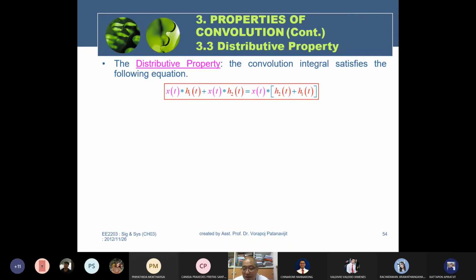But instead of considering it as a single large wide band, we separate it into small narrow bands, maybe 10, 100, or 1,000, and transmit each piece of the signal. Even if some band is interrupted or destroyed, you do not necessarily need to resend everything again. You send only the band that was incorrect.